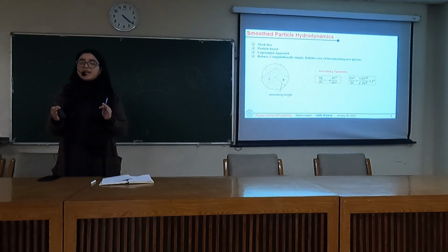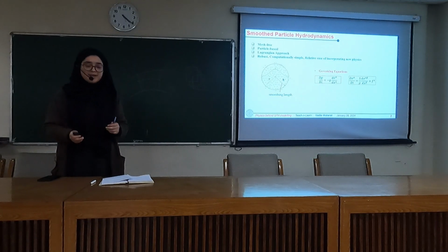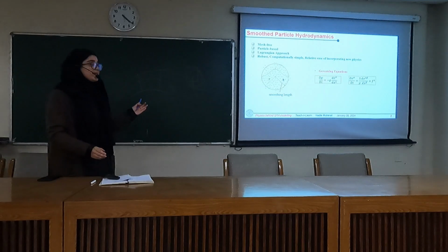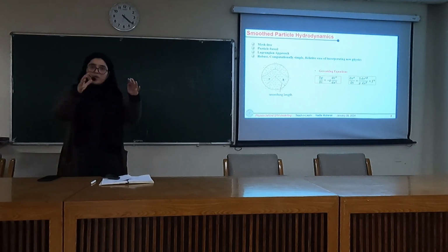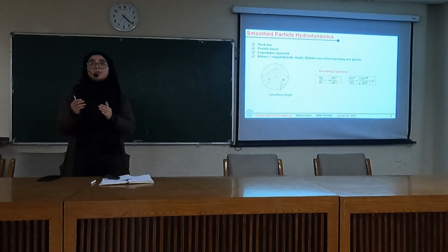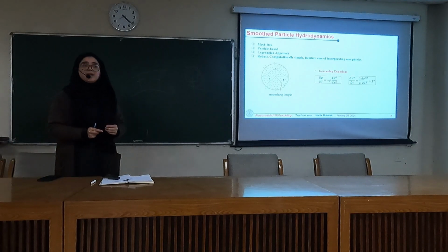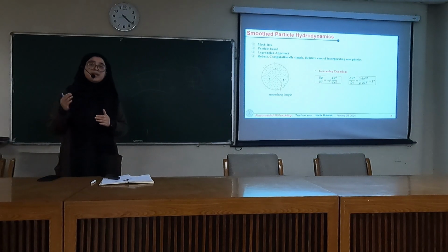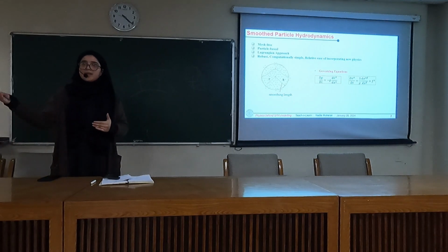The solution strategy for SPH uses an explicit integration scheme, which means that if we have these properties known at time t, the density, velocity, and all these parameters for the fluid, and we are able to calculate all these properties at time t plus delta t, then we should be able to calculate these properties at other time steps as well. This is how the process will continue.